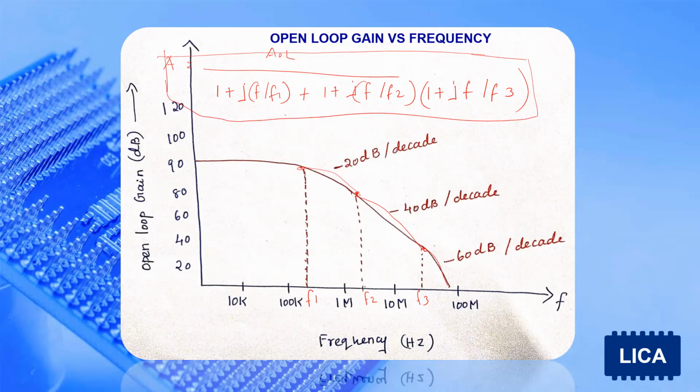Okay. So this is about the frequency response of AC characteristics. For the ideal case, gain will remain the same throughout the frequency range up to infinity. But for a practical case, it is not like that. The gain will roll down at a particular corner frequency. The roll down takes place because of the presence of capacitance elements.